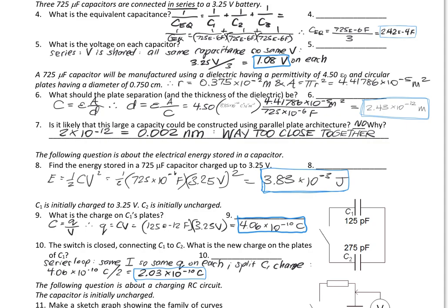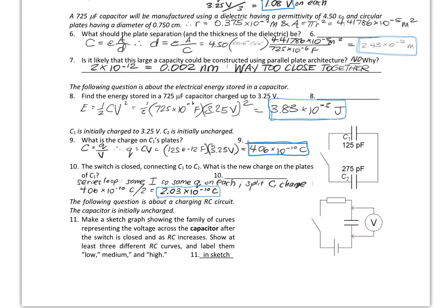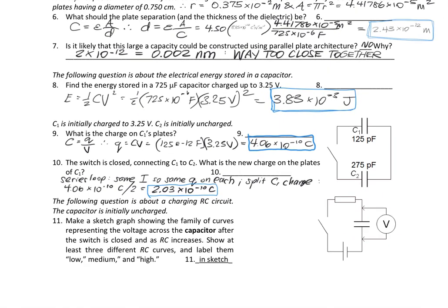If you actually look at the Lund notes that this question is based off of, Lund's analysis says that the two capacitors are in parallel. I would not call that parallel. That is a single loop, a single connection. That is the defining characteristic of a series circuit. And if it's a series circuit, they're going to have the same current in both of them.